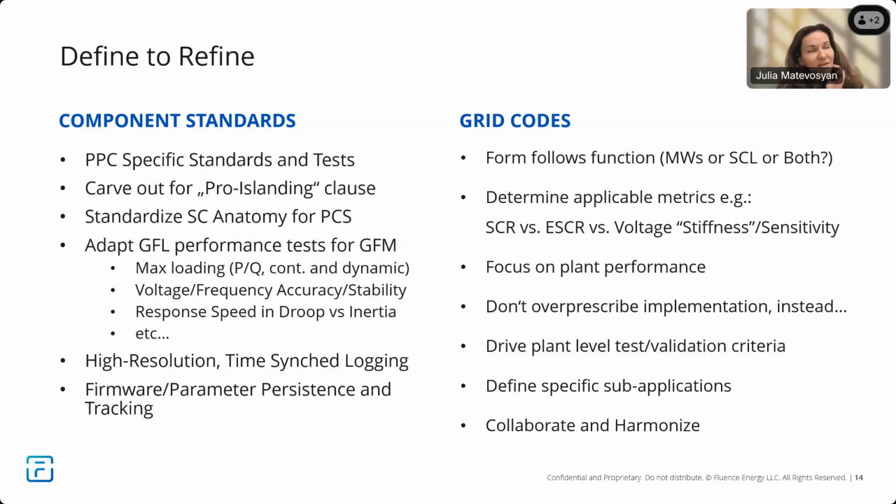One of the analogies I'm thinking about in that respect is primary frequency response, where you're requiring all resources to have the capability, but for a certain number of resources, maybe you have a market to actually have this capability available at all times, right? So you have it spread around a bigger pool of resources and not all of them hitting limits at the same time. But when they are, you also have this additional reserve, quote unquote, that you can tap into.